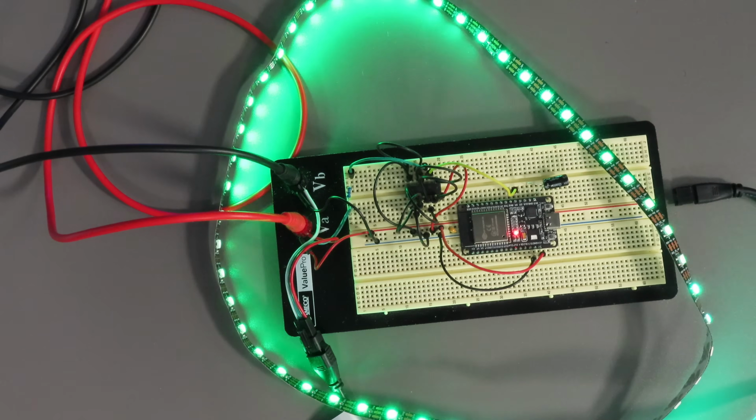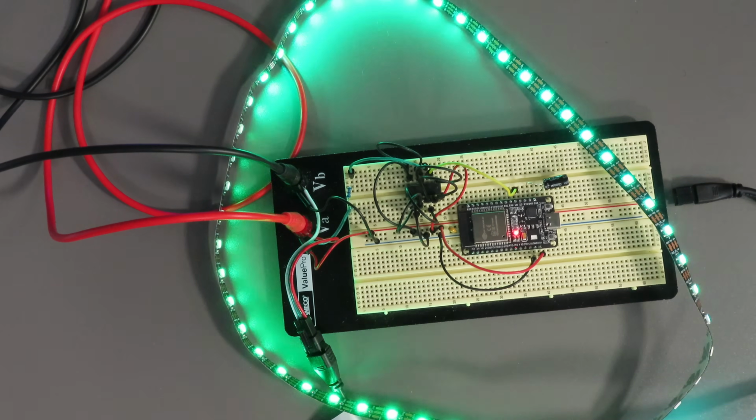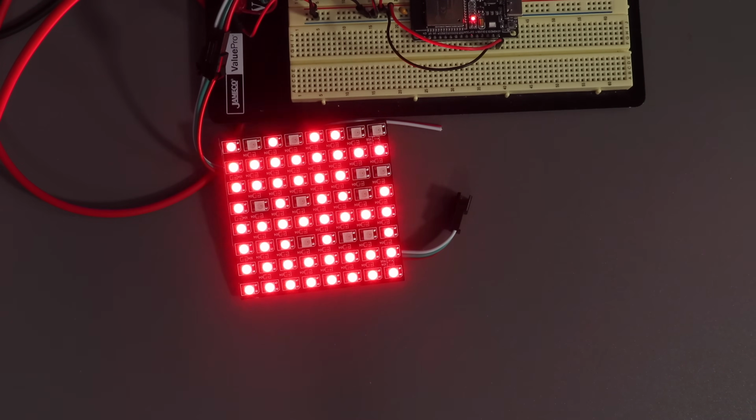So as you can see, with no code whatsoever, we have built a complete controller for LED strip lights using WLED. And so here's another demonstration. In this case, I've replaced my LED strip with one of the LED matrices I showed you earlier. Now the matrices are 8 by 8, so there are 64 LEDs on them, and the only change I needed to go into configuration was to go into my LED config and set it for 64 LEDs, because these are the same type of NeoPixels that my LED strip was.